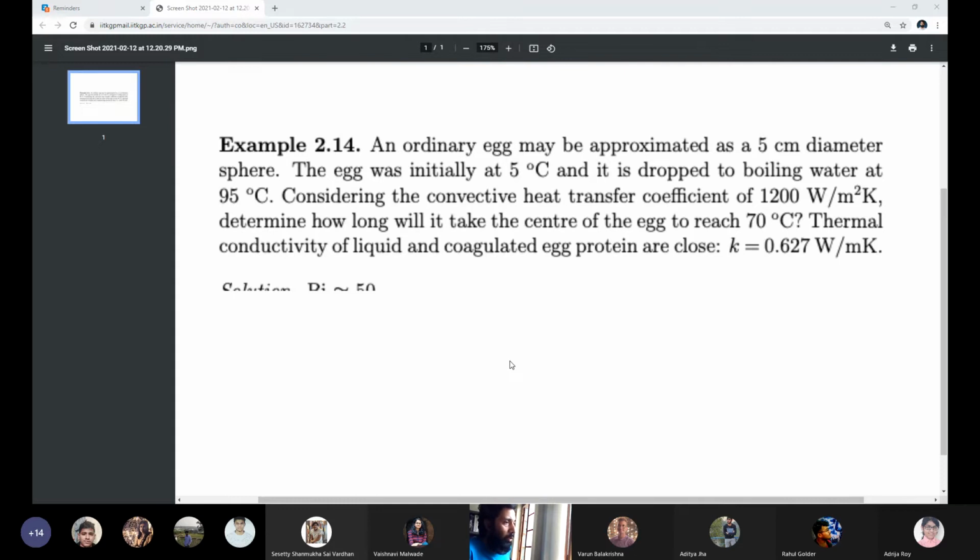So the Biot number you have calculated to be 47 point something. Now look at the chart and get what is your C1, what is the coefficient, and what is lambda. You can approximate it to be 50. For this class you can take that, otherwise you can take linear interpolation. Because we are solving a problem in class, take Biot number to be 50.